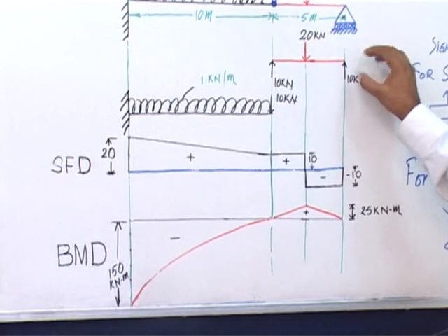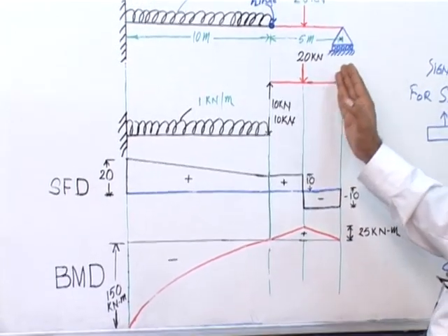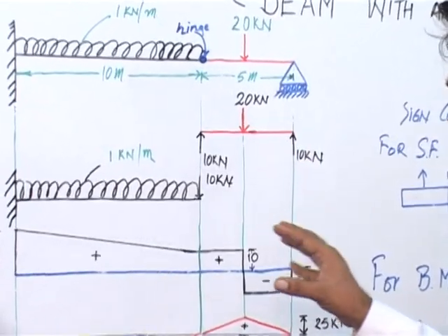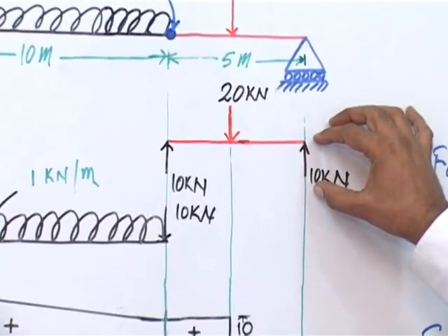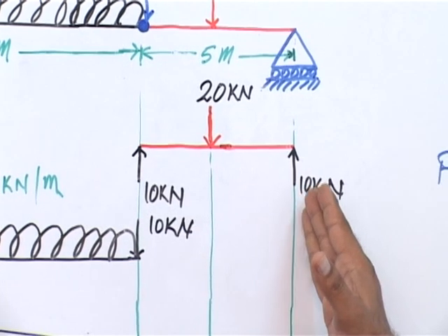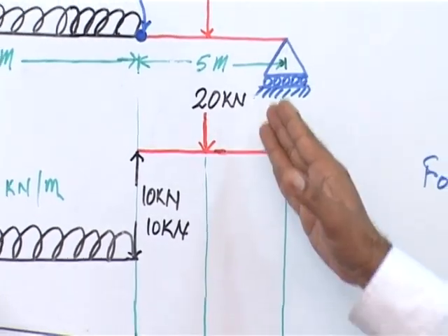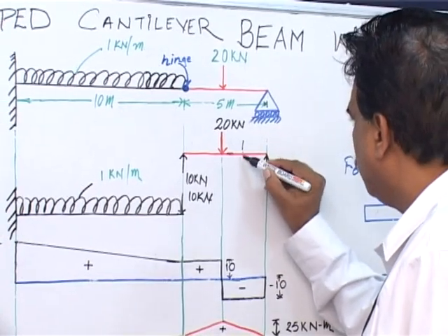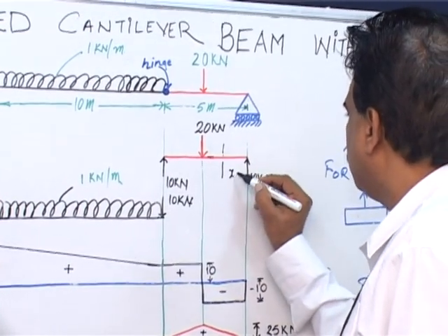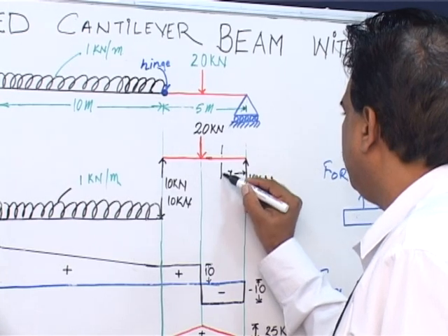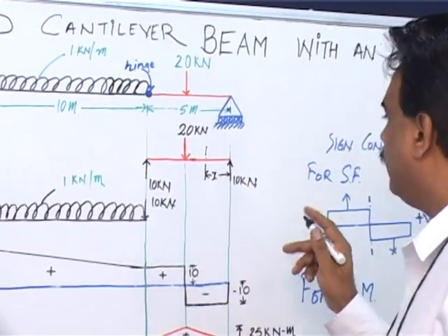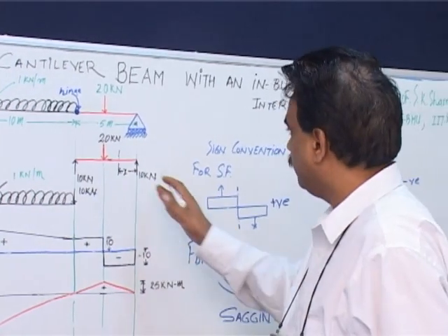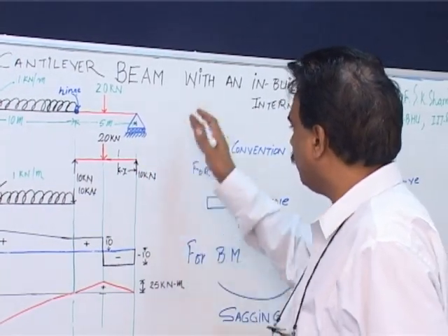Now, you have 10 kilonewtons. So as far as this beam is concerned, if we try to draw a shear force diagram, you have the 10 kilonewtons going upwards. So if we take any section, for example, a section here at a distance x from the right reaction, and if we consider the loads to the right of the section, then the right portion is going up.